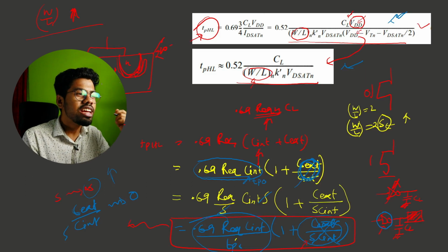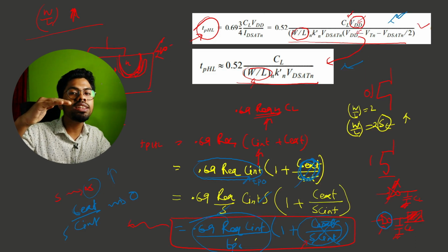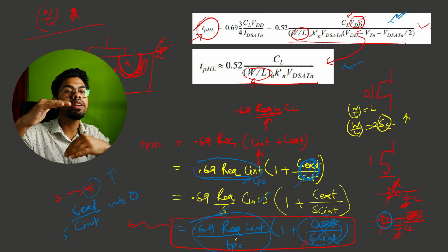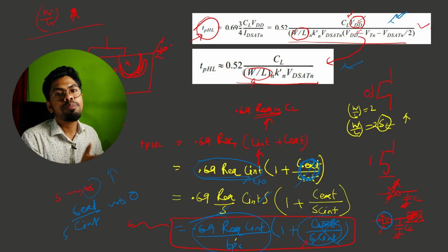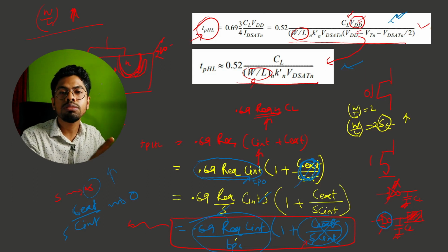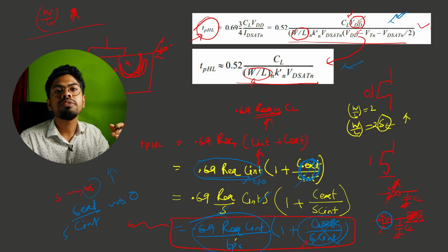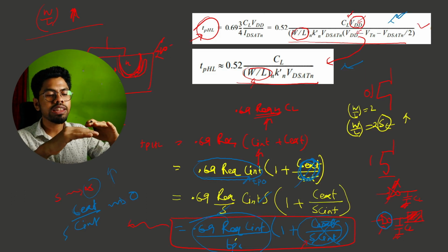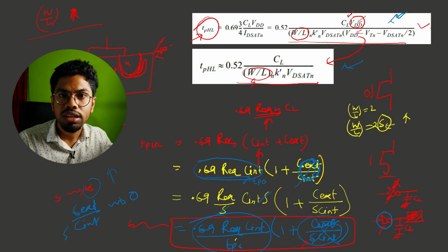And intuitively you can say yeah, if we have more voltage, more VDD, then it will feed more current, which will charge our capacitance in a faster way. This is just a quantitative analysis, I am not going deeply. But increasing VDD also has some concern, because we have an upper limit. After that, if we increase the VDD, it might burn out our devices.